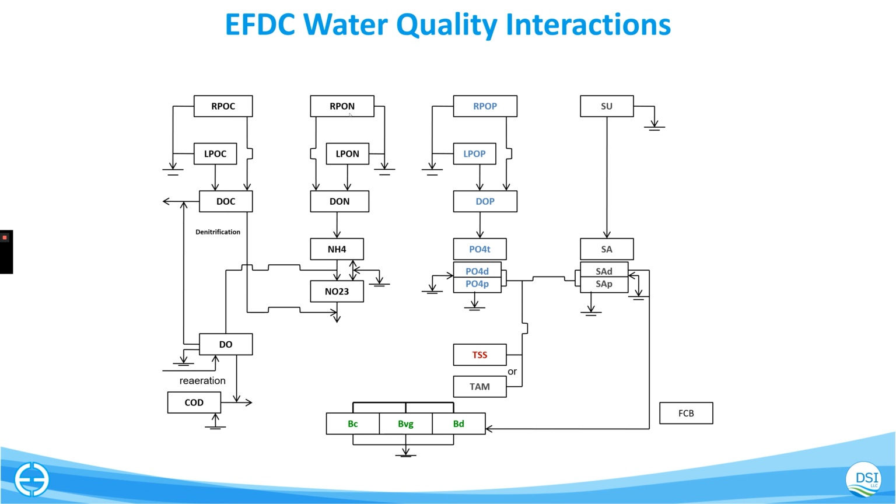So, moving on. This shows you the processes that are connected to the different algal groups, in more of a process term as opposed to just the state variables. Growth consumes ammonia and consumes NOx, and of course also consumes phosphate. In combination with light, through photosynthesis, you grow your algal groups and produce dissolved oxygen.